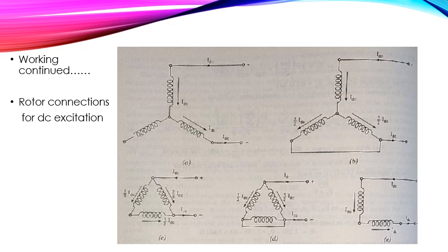So this is the answer to the question of why a very large air gap is provided in a synchronous induction motor. What is the reason for that? If a very short air gap is there, as in the plain induction motor, it will result in a very heavy armature reaction when operating as a synchronous motor, because the total field ampere turns would be reduced for a given number of armature ampere turns.